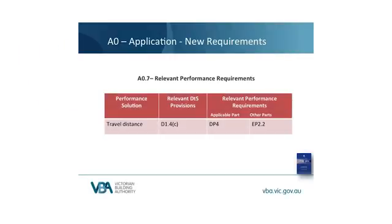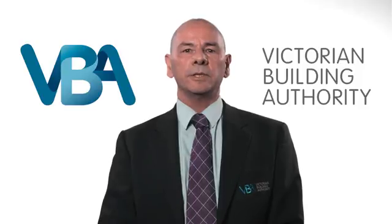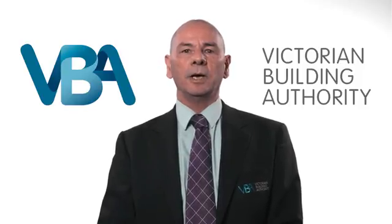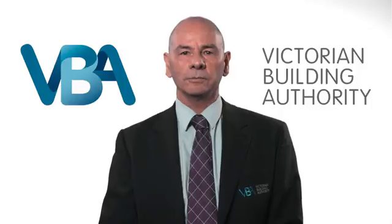Explanation of A0.7. When you assess a performance solution report, you are likely to find a table like this one somewhere near the front. This table responds to A0.10, or what in NCC 2016 has been relocated to A0.7b. This is the provision which requires that when a performance solution is designed, then the relevant deemed to satisfy provisions need to be identified as well as the performance requirements relevant to the performance solution.